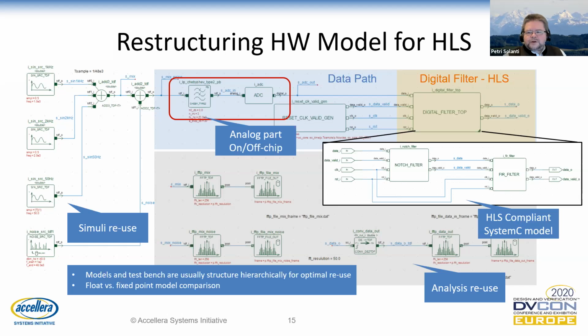If the digital part is written using synthesizable floating point data types, it can be synthesized to see if there are any coding style issues. Usually, the separation of the test bench and DUT and the separation between analog, digital, and software parts is expressed by a hierarchical structuring approach. But in this example, it is left flat to have the overview on one slide.